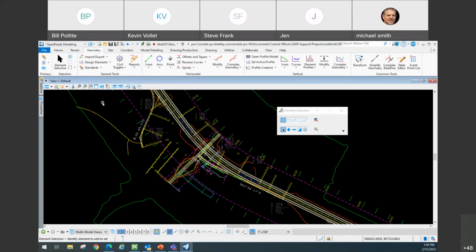Okay, cool. And that would be an ORD feature definition. So if they converted your job up and it's still an SS10 feature definition, they would have to probably change that to an ORD feature definition. So yeah, it's going to have to be from the ORD. That's correct. Yep. Okay.